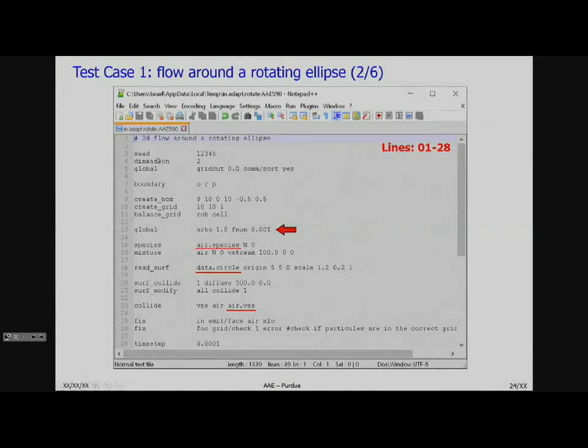So you set up, so here dimension problem, do you want a 2D or 3D problem? Those are your only options. If you want a 1D problem or a 0D problem, you make it 2D and then you set the boundary conditions such that it acts like a 1D or 0D problem. The boundary conditions here: O is outflow, R is reflective or specular, P is periodic, there's also S for surface, and there's A for axisymmetric.